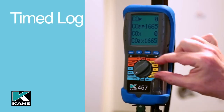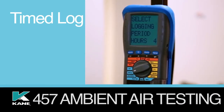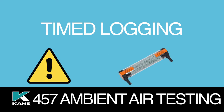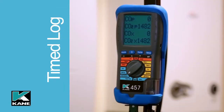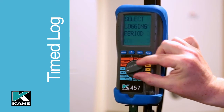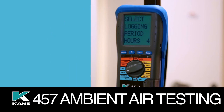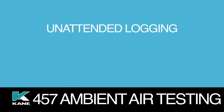The next position is timed logging. Note, before carrying out this test and to ensure accurate ambient measurements of CO2, the KANE457 should always be zeroed using a zero cal capsule. We will demonstrate how to do this in a few minutes. There are situations when CO and CO2 readings may need to be taken over specific periods of time to establish a profile of concentrations. The KANE457 allows for unattended timed monitoring and logging periods ranging from 4 hours to 24 hours.